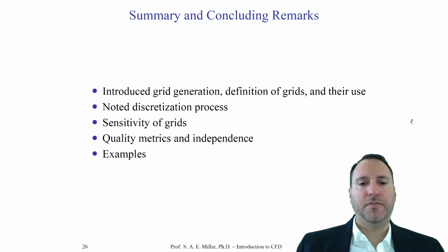This might involve advancing methods where you have boundary layer refinement, wake refinement, or trying to put grid points around shock waves. This is a very detailed process that can really only be learned with experience, which we'll be trying in this class so you get a taste of what it is.